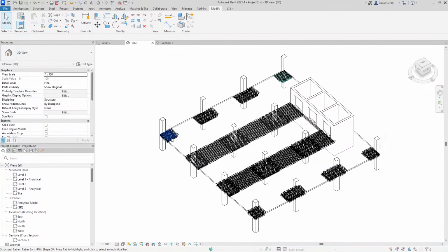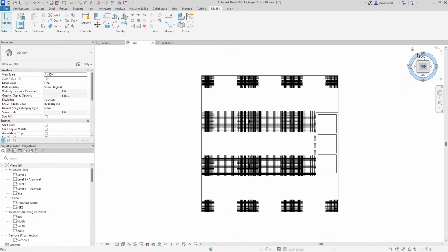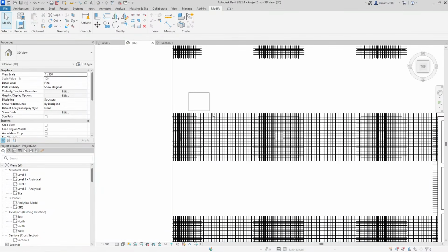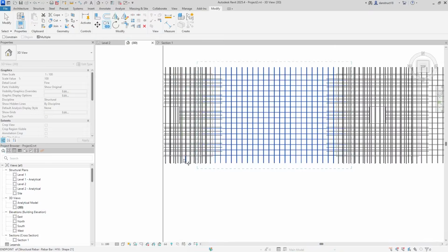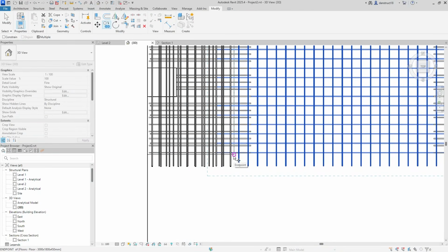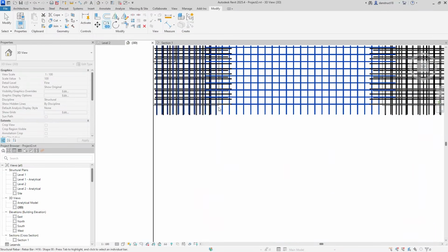Now let's go ahead and place the support reinforcements. When I say support, I mean the middle, or rather the column strip reinforcements at the edges. And what I'm going to do is make a selection of these bars here. I'll click on the top view. Keep in mind we're oriented not in this direction. And I'll make a selection over the bars like this. Okay, and you can see here that we have 4 rebars in sets. All right, with them being selected, I'm just going to click here on copy. There we go. And I'm going to come to the end of this drop panel, click there as a reference, and then click here and press escape.